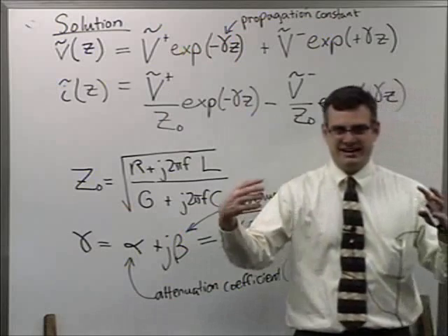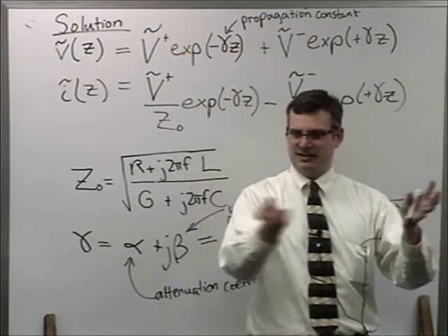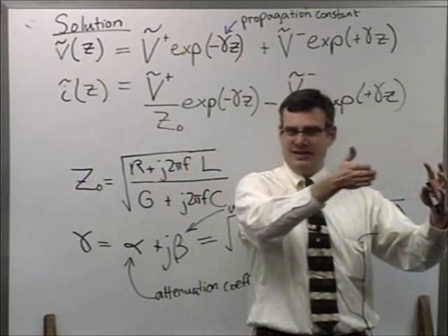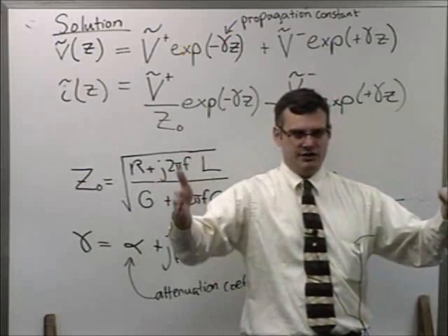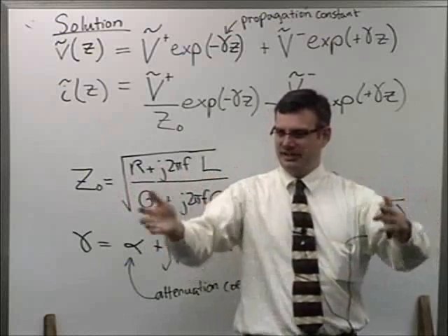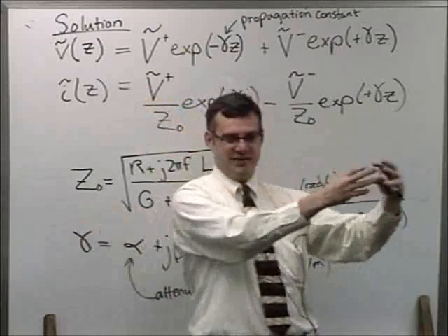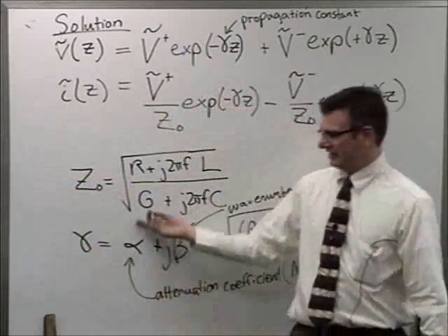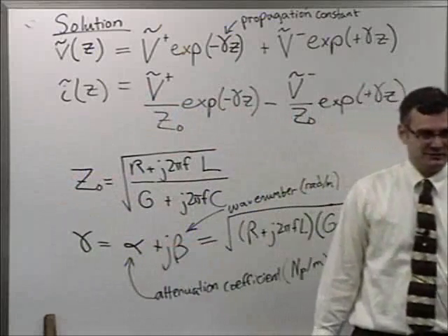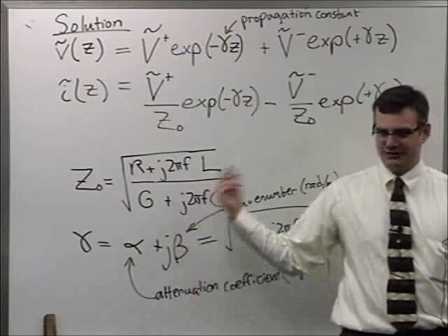And there's a section of line that they excite with a laser. They pump up these erbium doped atoms in an optical fiber. And so they're kind of stimulated, right? And as an optical pulse goes through them, it's almost like an unconfined laser cavity. The excited erbium atoms give stimulated emission, which will actually amplify the wave. So you get exponential increase of your signal as you go down that particular type of guided wave structure. You can model it with transmission line equations and use a negative alpha for that particular system. It's a very artificial way to make a negative alpha, but it sometimes happens that such systems can be modeled in that manner.